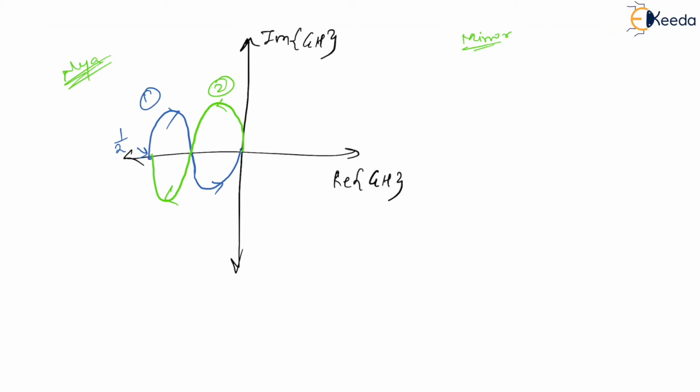Yes. Now see dear, what about encirclements? If you see, half is here, half is lying here, which means somewhere around here I should be having -1, right? Yes. Now -1 should be somewhere here, means this axis, if it goes this way. So if you see, there are no encirclements around -1. It indicates that encirclements N is equal to 0. Because by the trick, if I check this one to be like this, then there is no intersection to it, right? Which means N is equal to 0.